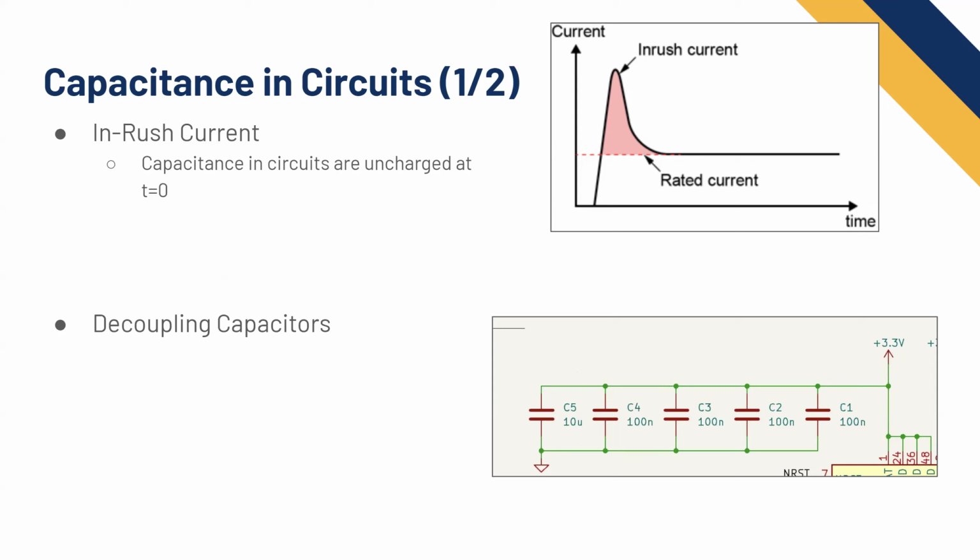When you suddenly pull a lot more current than you were before, that's going to be an instantaneous change in current. And so the inductor, like we said, doesn't like that. It won't be able to instantaneously source that current. It's going to take some time to build up that magnetic field energy. And so the voltage at your node is going to drop because you have a big dI/dt, and right, we said before, voltage is equal to inductance times the change in current. So if you have a big dI/dt times your inductance, you're going to have a voltage drop across it.